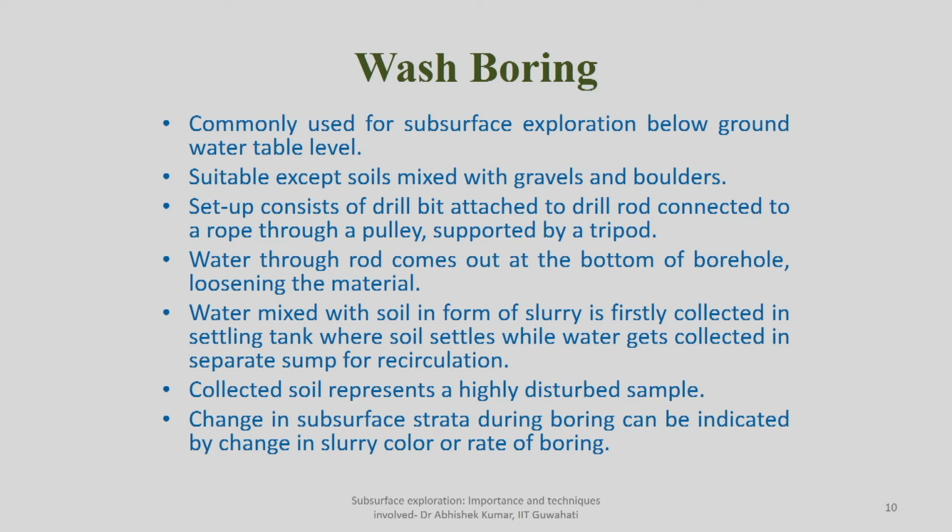If you have some collapsible or cohesionless soil available at the ground surface, you first lower some casing and then you start boring by means of any of those augers. The second method of boring is wash boring. It is commonly used for subsurface exploration below the groundwater table.